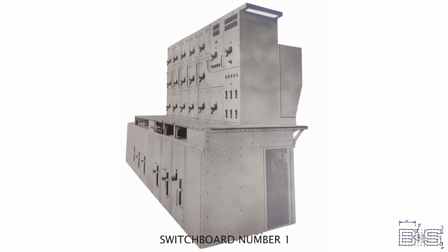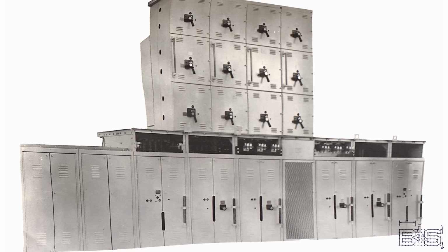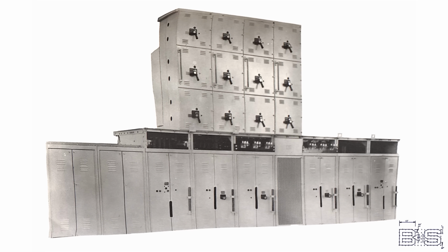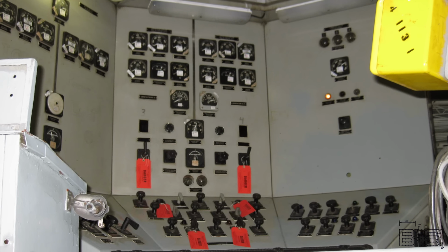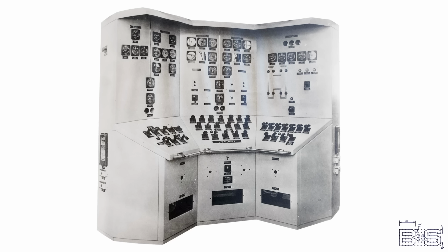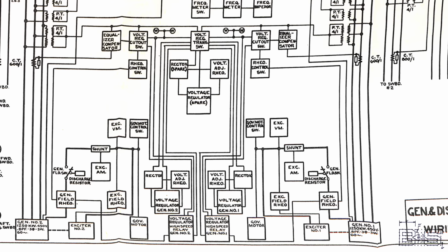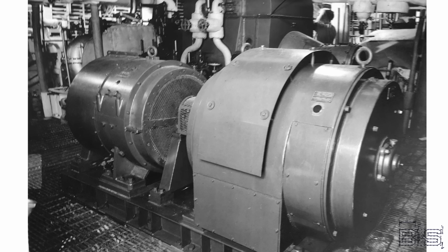Every engine room in an Iowa-class battleship has 2 turbo generators and 1 distribution switchboard. The distribution section is on the top, and the larger motor-operated circuit breakers are on the lower level. The controls are in a separate bench board that sits on the upper level. The master and load control assignments are the same as on the South Dakotas, but everything is located in the engine rooms, including the ship's service motor generator sets.